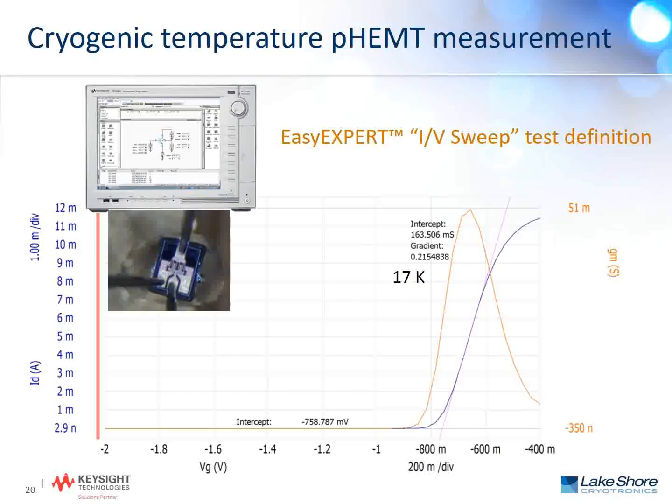Now conventionally, for a cryogenic device measurement, we land our probes at a given temperature, and then before we move to the next temperature, we would have to lift those probes, move to the next temperature, let the sample stage come to equilibrium, and then re-land the probes onto the devices. For a device measurement over a wide range of temperatures with reasonable temperature sensitivity, it actually results in a large number of lifting and re-landing cycles. It's actually pretty inefficient when it comes to doing a device scale measurement.